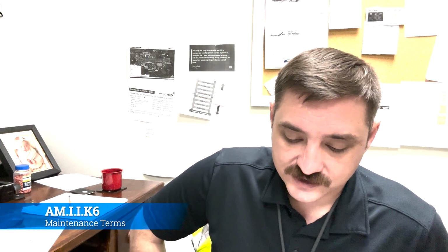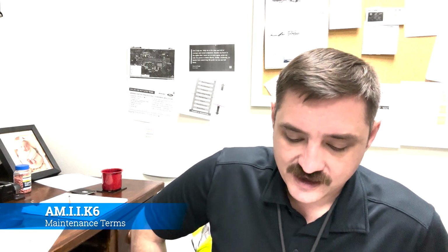An ETOPS Group 1 significant system has fail-safe characteristics directly linked to the degree of redundancy provided by the number of engines on an airplane. It is a system the failure or malfunction of which could result in an IFSD, loss of thrust control, or power loss; contributes significantly to the safety of an ETOPS diversion by providing additional redundancy for any system power source loss as a result of an inoperative engine; and is essential for prolonged operation of an engine at engine inoperative altitudes.